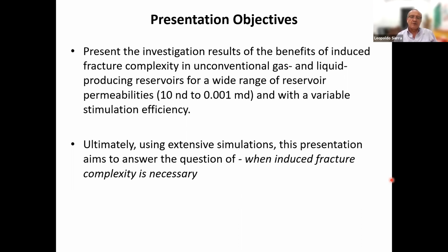To do that, we used two cases, the unconventional gas and unconventional liquid producer reservoirs, for a wide range of permeabilities changing from 10 nanodarcies to 1,000 nanodarcies, and also considering the stimulation efficiencies. We were able to get a good observation that in some cases the fracture complexity is not totally necessary.